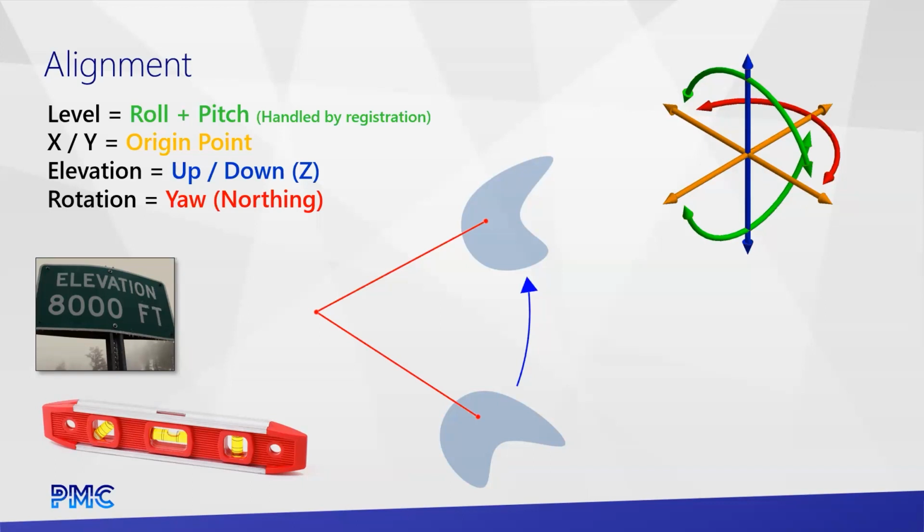If you screw the alignment up and it doesn't match up to your expectations, all of the post-processing work that on bigger jobs can take weeks has to be completely redone to adjust the alignment. So make sure you spend some time, make sure you agree on what's our origin point, which way points north in the building, and where do you want your elevation? And then importantly, what point is your origin point and what point is your elevation going to be set to?